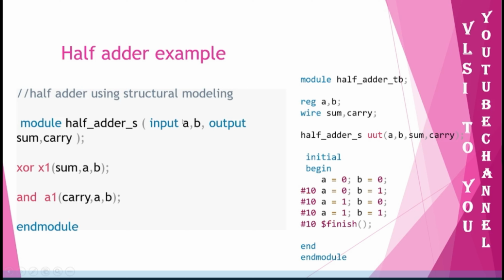So reg a, b, since they are inputs, are mentioned as reg, and the outputs are mentioned as wire. You don't give inputs and outputs in the test bench, because the test bench is only used to pass the values into that particular DUT. As a beginner you should know that, because many of you get confused and declare them as input and output. You should not mention any inputs and outputs within your test bench, because the test bench is nothing but an environment where you will be passing the values to the DUT. You don't do anything related to input and output within your test bench, right?